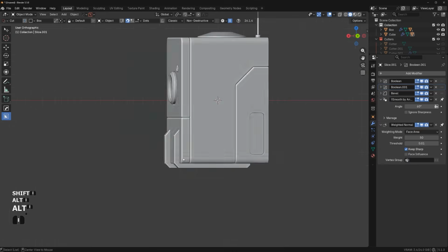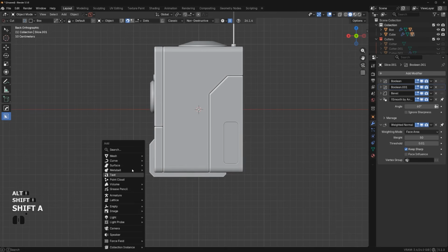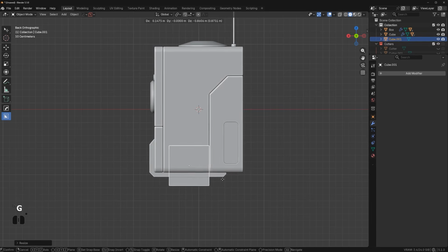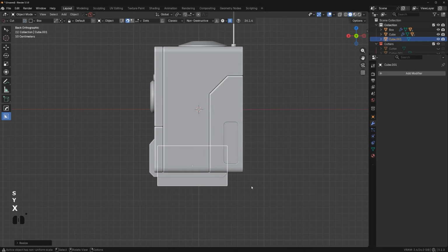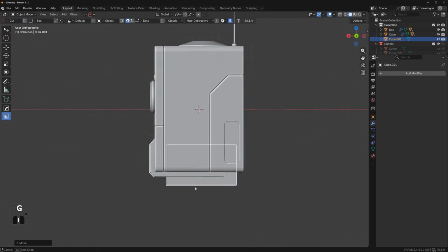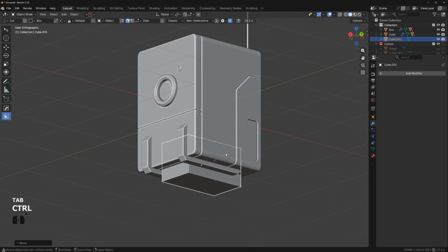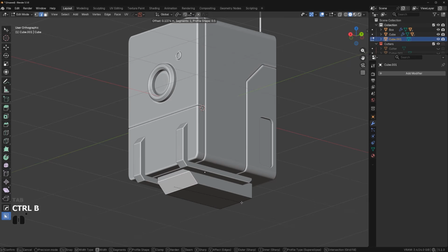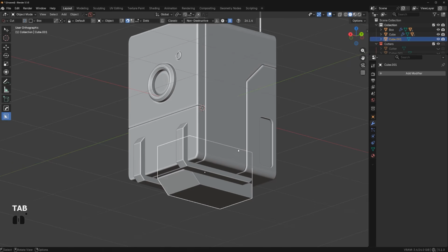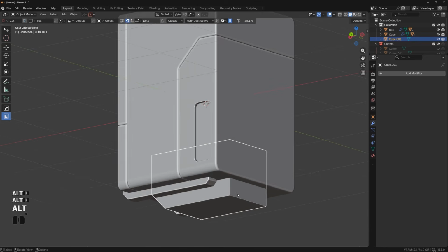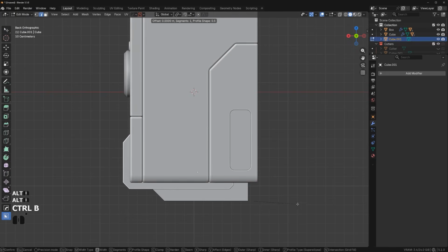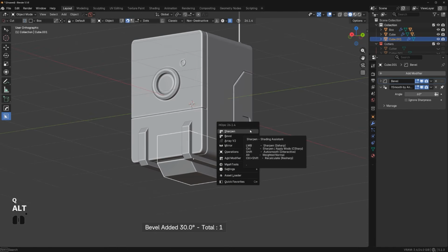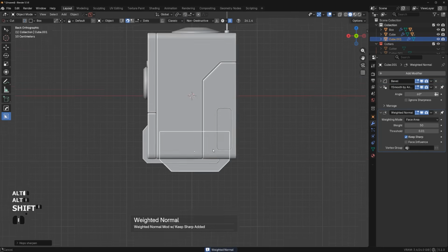And now we're going to create some simple legs, right? So let's grab a cube and scale it and pop it somewhere here. SY or SX. There we go, right? Let's actually apply scale. So Control A, apply scale to unify it. Go to edge mode and Control B to chamfer this. And this could be chamfered as well, to be honest. There we go. And we can bevel this. And Alt click on sharpen to introduce weighted normals.